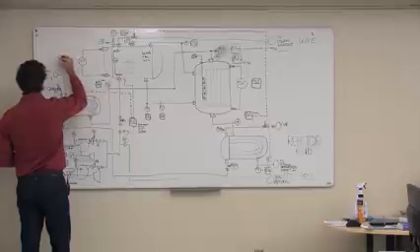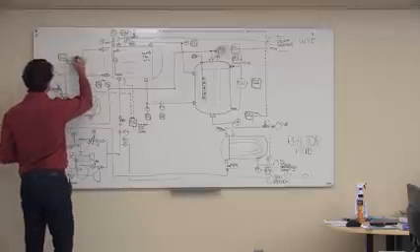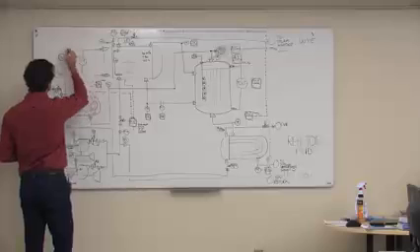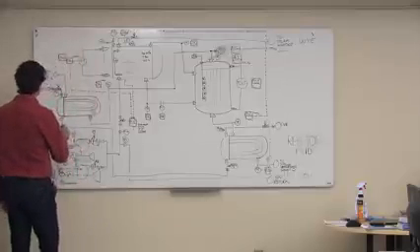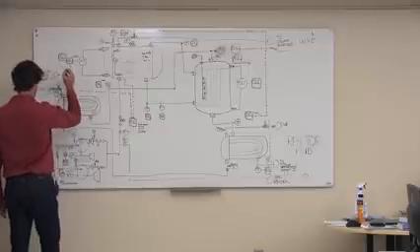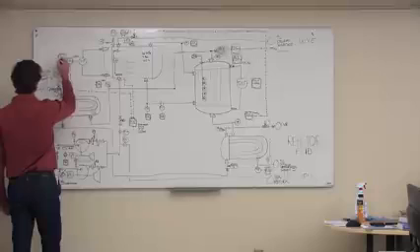Let's make it a low. Okay, this will have a level alarm high and a low. And then that level switch low, we maybe want to tie into starting the pumps. So we're going to do that basically by tying the control systems in here.